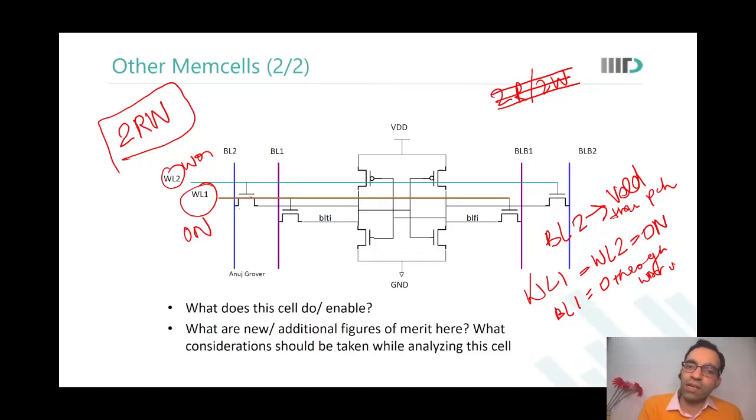So when one of the word lines goes on, suppose there was a 0 stored here, what will it do? It will discharge this and it will discharge this also. Now you wanted to store a 1 here. Now the bit lines are discharged. The Vx was initially something, but it now falls because the bit lines have discharged. So it is Vx minus.